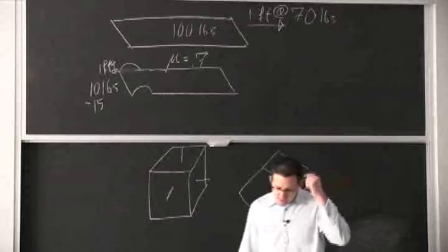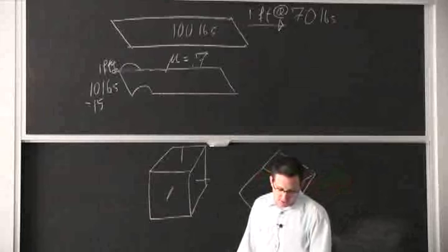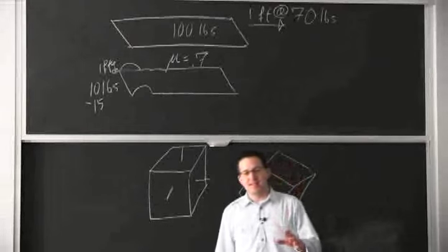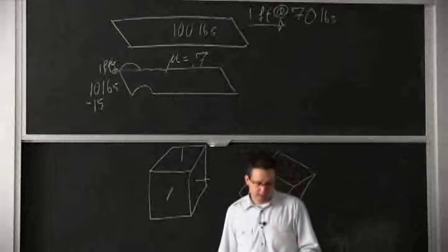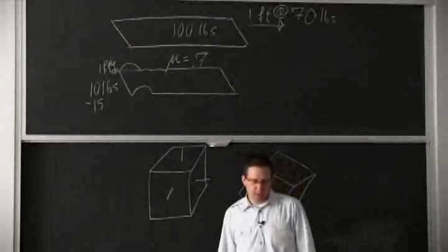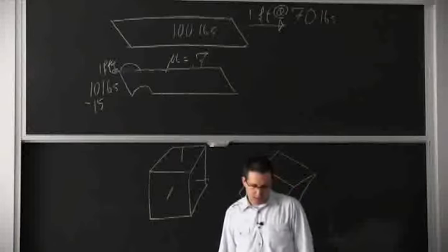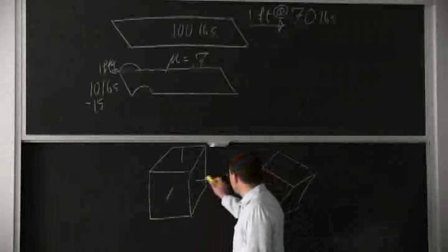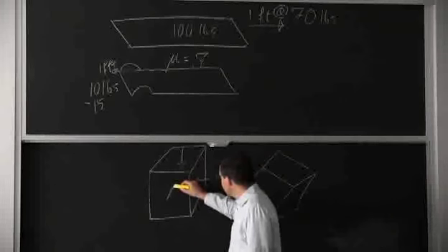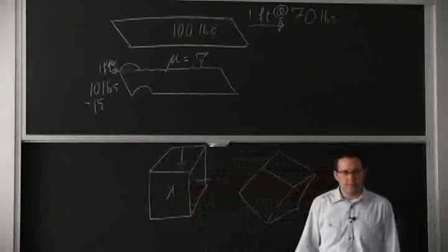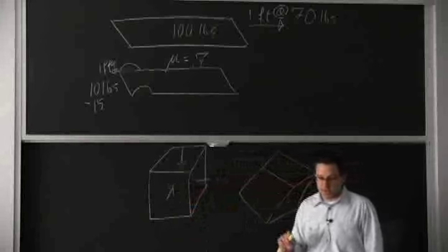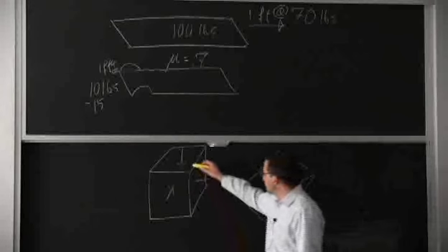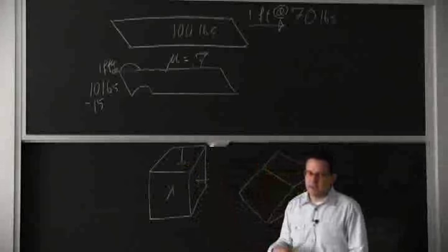And I pulled a little schematic for you in the middle of the page where if you are inside that cylinder, the cylinder has an axis that's right in the middle between sigma 1, sigma 2, and sigma 3. If you're in there, you can put as much stress as you want. You can compress this, or you can put tension on it. It will not yield. But with the differences, there's only so far you can go when you start having a difference between this one, and then you'll start yielding.